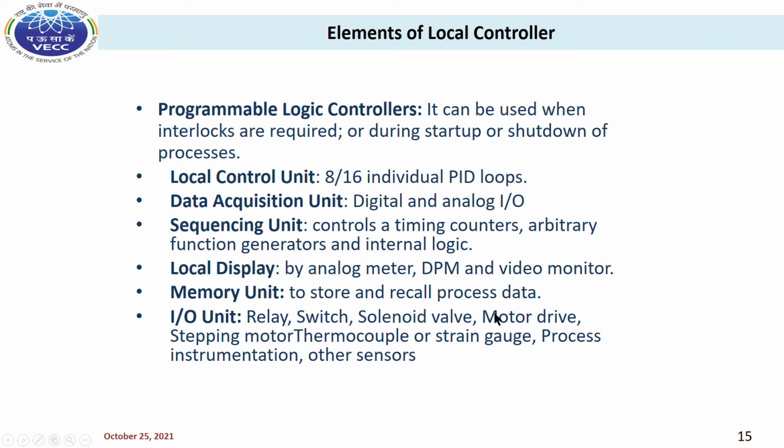The components of a PLC are the power supply, input output section, processor, and programming section. The difference between a PLC and an embedded system or single board computer is that in the PLC controller unit, several PID loops can run simultaneously. Another important feature is the sequencer.